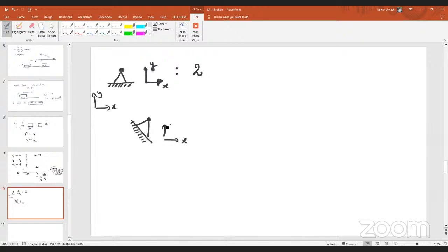Is it the same? No, sir. Then what is the best way to describe the type of force a hinge gives? Always you have to talk about parallel to the surface and perpendicular to the surface. If I'm talking about the surface of the hinge joint, I can say one force might be parallel to this surface and one force will be perpendicular to this surface.